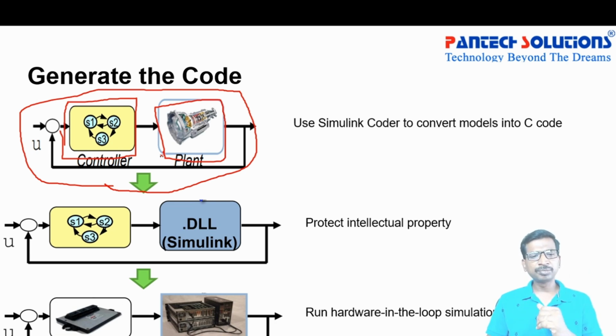They can take output from the model. So similarly, you can generate code. For this entire block, you can generate a .c file or .hex file or .out file, based on the hardware output. I will tell you one by one.